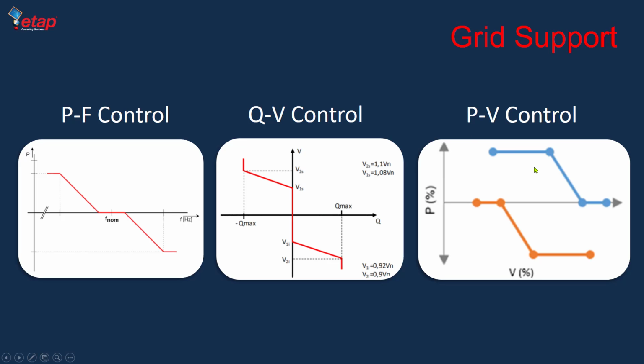Okay. Now, in the distribution system application, in the microgrid application where the X/R ratios are low, what happens is that there is no one-to-one relationship between active power and frequency and reactive power and voltage, and these are not fully decoupled. So it seems that it's better also to have a power and voltage control.